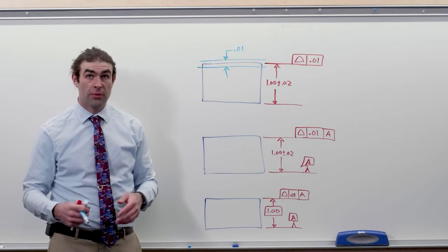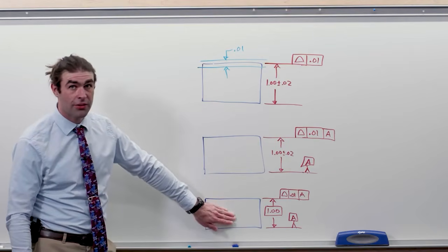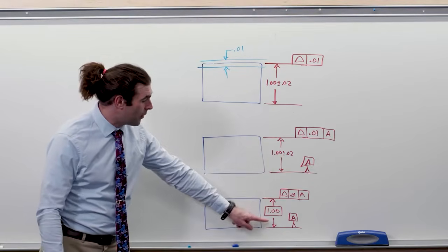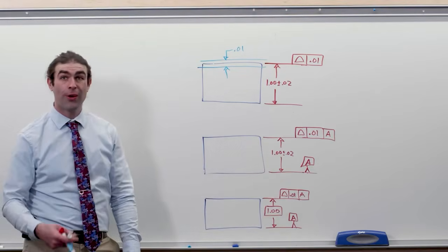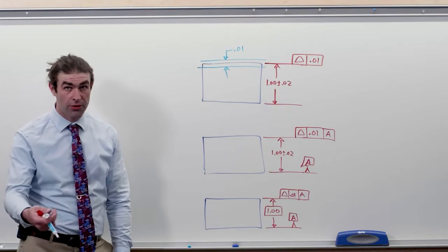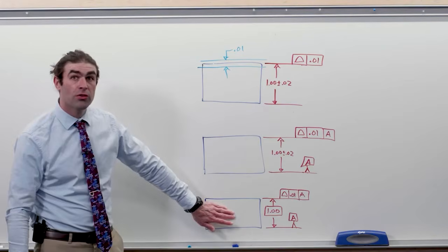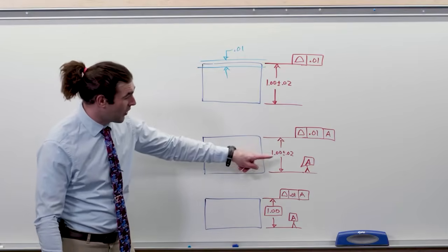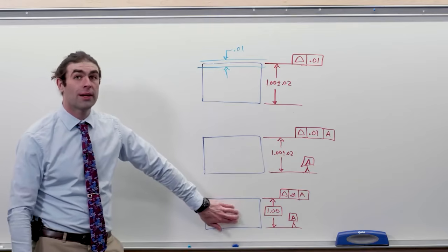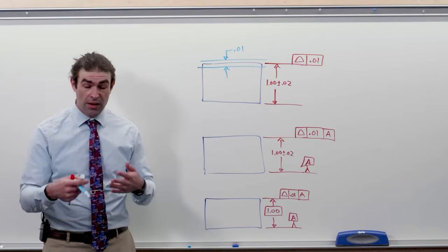You should use a basic dimension, but when we do the right thing and use a basic dimension, if you notice, all of this tolerance went away. Now, the profile is controlling the location of that surface, as well as the size, as well as the form, and the parallelism. It makes it much more restrictive. Even though all we did was change from a plus or minus to a basic dimension, this becomes a much more restrictive tolerance. Now, we can fix that with a composite profile.